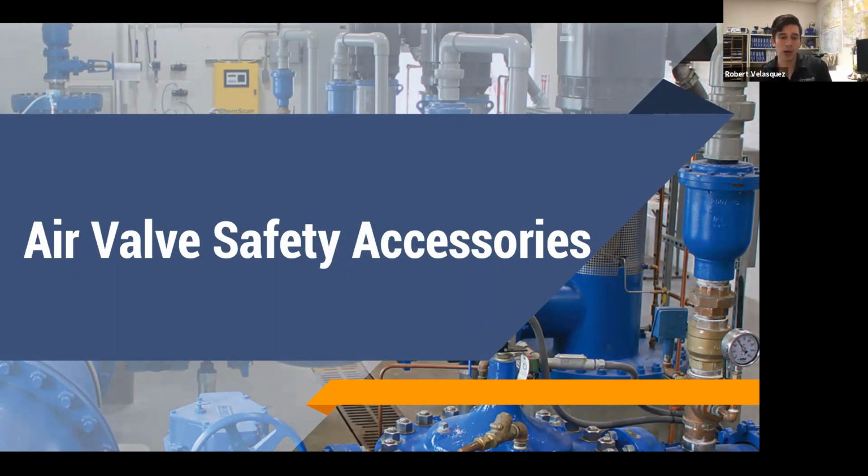So one of the common ways to fix this problem that a lot of water districts and engineers did is that you would take the pipe from the top of your air vacuum valve and you just pipe it up out of your vault, up above ground, and maybe have it flip around to protect from rainwater getting into it. So that now protects from your vault flooding and getting a cross-contamination risk, right? Yes, but it also creates a whole other safety risk.